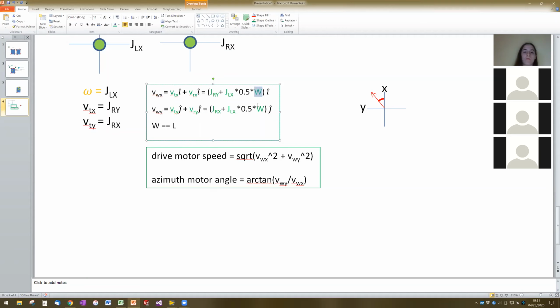And so we have two options. The first option that Lindsay suggests is we could convert the joystick values into velocities. So instead of it going from -1 to 1, it would instead go from -20 feet per second to +20 feet per second, or the equivalent of that in inches per second. And that would be totally valid, and that would be a better approach than what we're doing right now, and it would sort of go back into what we talked about last session about, instead of setting a power on the drive motors, setting a goal speed.